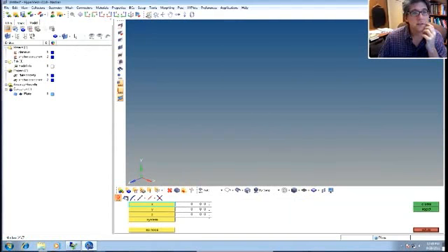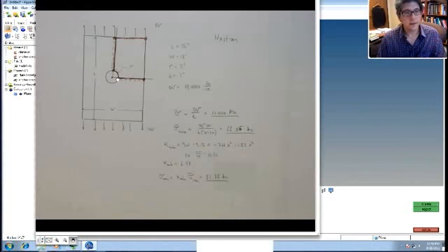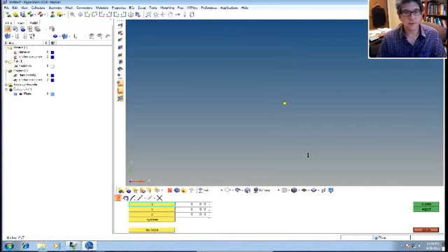And I think we should see it. Let's change the orientation. So I'm looking down the z-axis. Okay. And here's the node I just created. That's the center of the circle. So let's make this right edge point of the circle. So we'll make this point. So that's going to be at the radius, and then 0, and then we'll go out here to W on 2, so on and so forth.